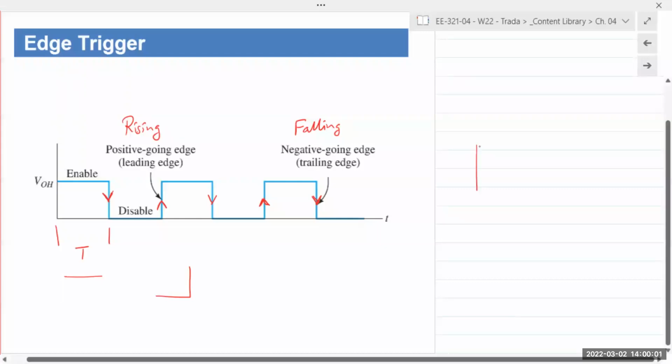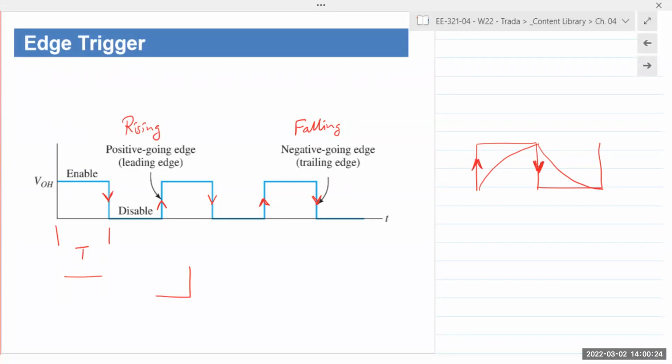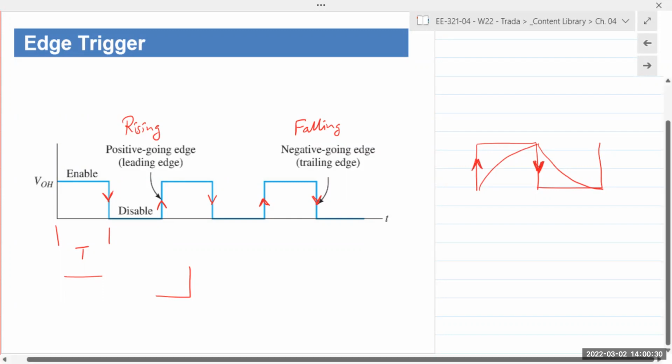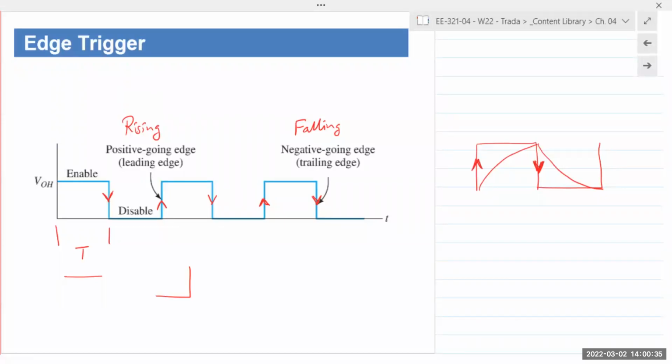And so you would set, if this was the waveform, the charging of the capacitor was like this, exponential, discharging was this. So you set the trigger to the rising edge to calculate the charging time constant. And you set the trigger to the falling edge to find the discharging time constant. That's where you had used it. It just basically moves the cursor and attaches it to that place. But anyway, the larger purpose is to basically synchronize all the circuits and to avoid confusion or unpredictable states in the circuit. Okay, unpredictable states.